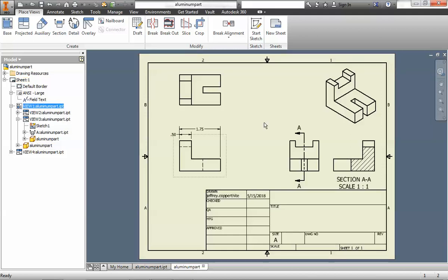All right, so anyway, that is how you're going to be placing views on here. Now, when you do these drawings, you're going to want to place as many views as are needed. So you may choose top, front, right is sufficient. You may think that top and front are okay. If you have something cylindrical, you may only need 2 views as an example. But generally, top, front, and right views are going to be what you'll need to place on your drawings, and then an isometric view. Never add dimensions to the isometric view. Make sure the dimensions are always on the orthographic projections.